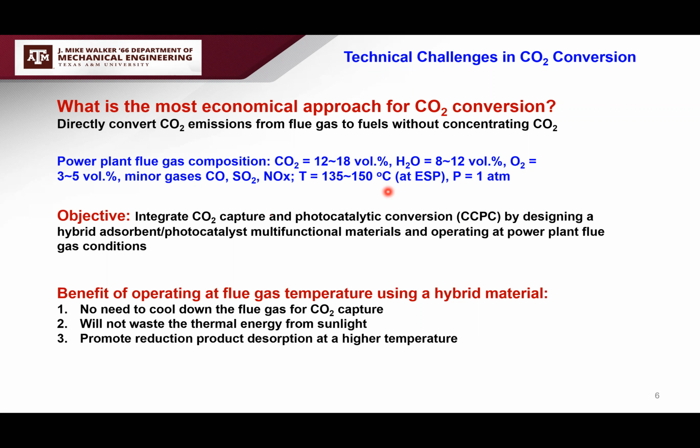Right? And so my thought was, can we integrate this CO2 capture and photocatalytic conversion process by designing just one hybrid material with adsorbent and photocatalysis components together, and then tune this catalyst so that it can operate at power plant flue gas conditions? By doing that, you don't have to cool down flue gas for CO2 capture, which is typically required if you use amine-based sorbent. So no cooling is needed.